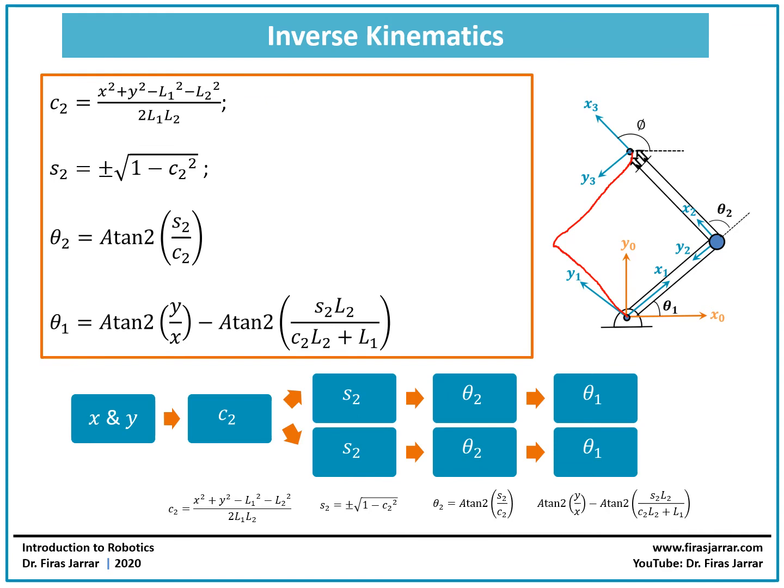Let me change the color of it. So theta 1 in this case becomes this angle, and for theta 2 you first have to extend L1, and theta 2 will be measured from here towards here. So this is the whole theta 2. So you can see that I have two solutions that will give me the same end effector position.